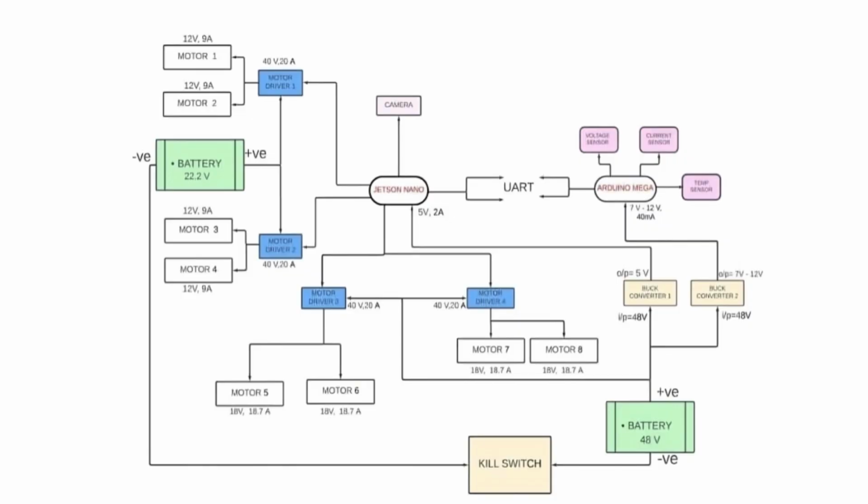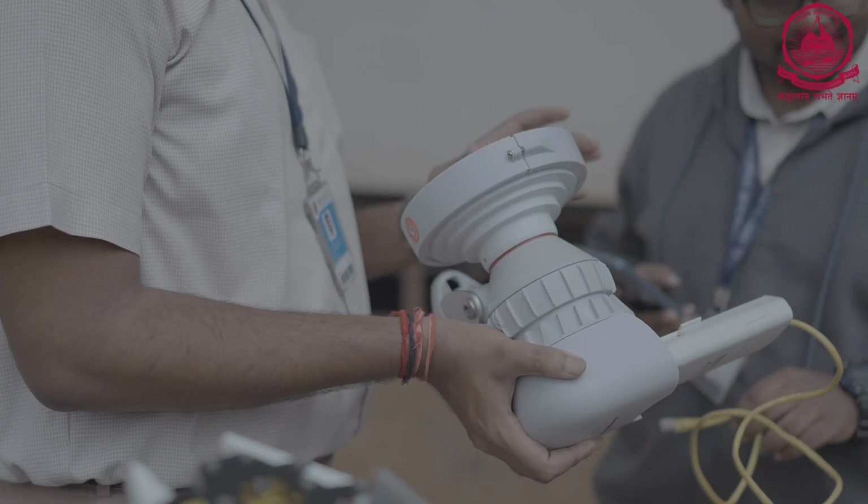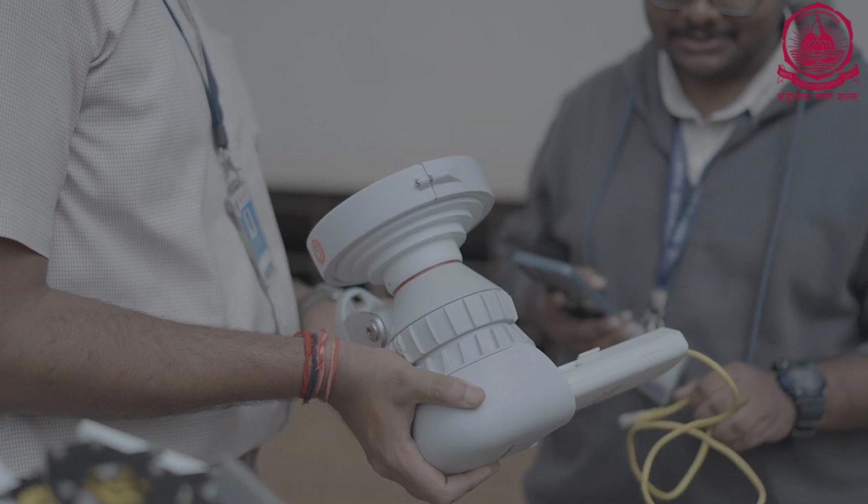Hi, the electrical and electronic subsystem integrates components for power management, sensor integration and communication aspects. For the power management system, we are implementing battery management for efficient power distribution throughout the rover. For the communication aspect, we are using 2 antennas. One antenna goes on the rover and the other antenna will be at the base station, working in a 5.8 GHz range.